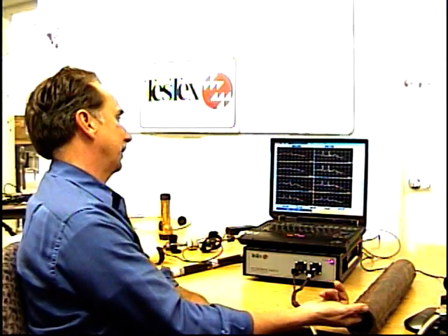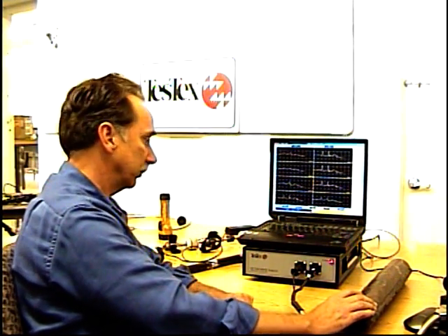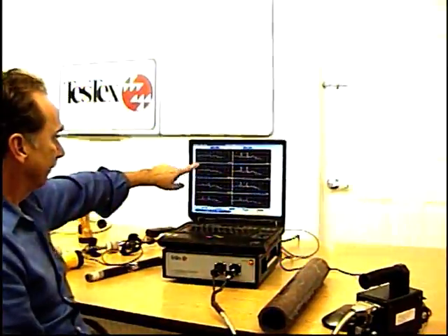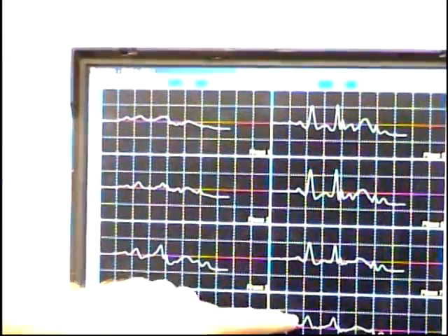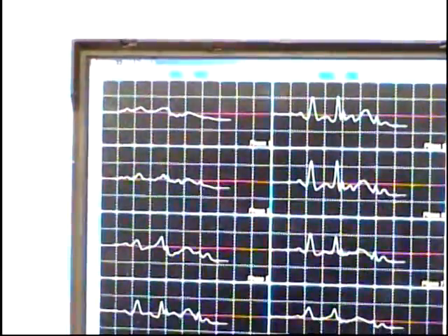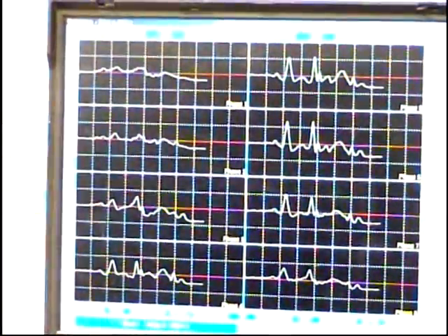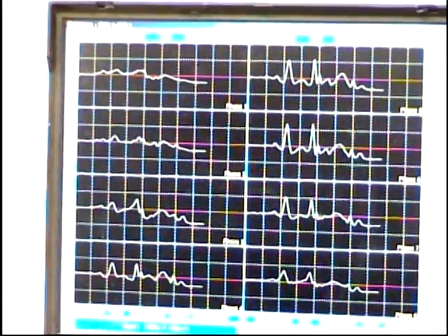Now this one typically has corrosion, so there's going to be wall loss associated. If you put a UT meter in, some of these indications here are going to show you almost over 50% wall loss in the tubes. But you notice each channel is affected differently. The first couple channels and the last channel show very little as far as the signal goes as far as wall loss. But once you get in the middle channels, you're going to notice how big the signal is. That's because in the middle of the tube is where most of the wall loss is.